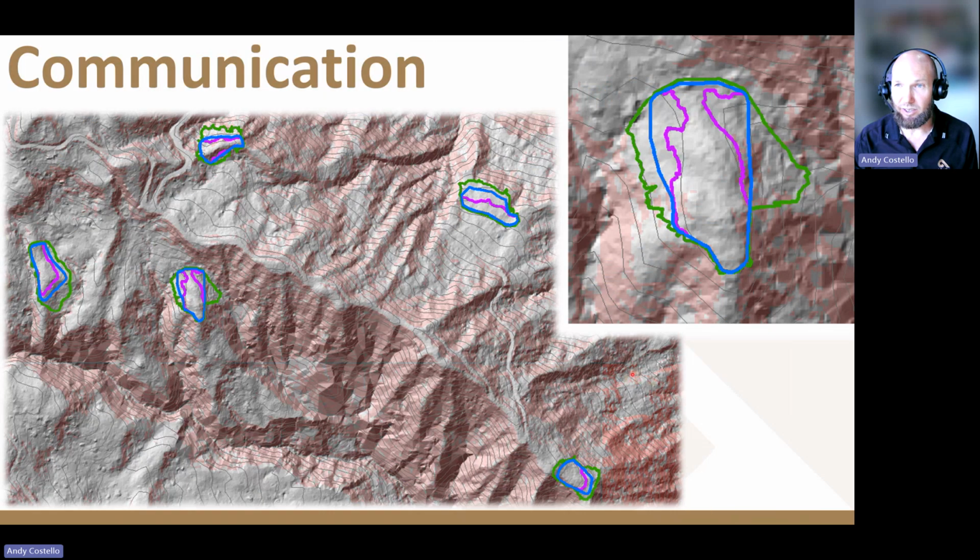We also communicate our skids. We do this with the high resolution GPS. The green line again is the earthworks extent. Again, for the road line crews, you've got to take at least this many trees off, got to clear this area. And then for the road builders, put your toe bench here. The purple line is out of road edge. That's where the cut turns into fill.